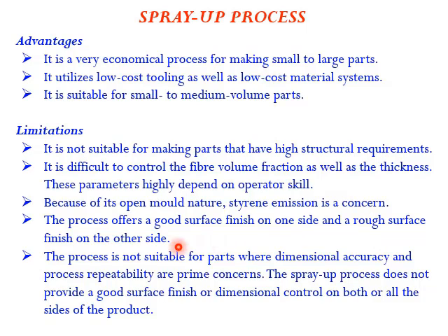The process offers a good surface finish on one side and a rough surface finish on the other side. When we spray against a wall, the surface which is in contact with the mold surface will get a good surface finish, and the surface outside will not have a good surface finish. To improve that, the roller is applied externally, in order to make sure that surface also becomes a good one.